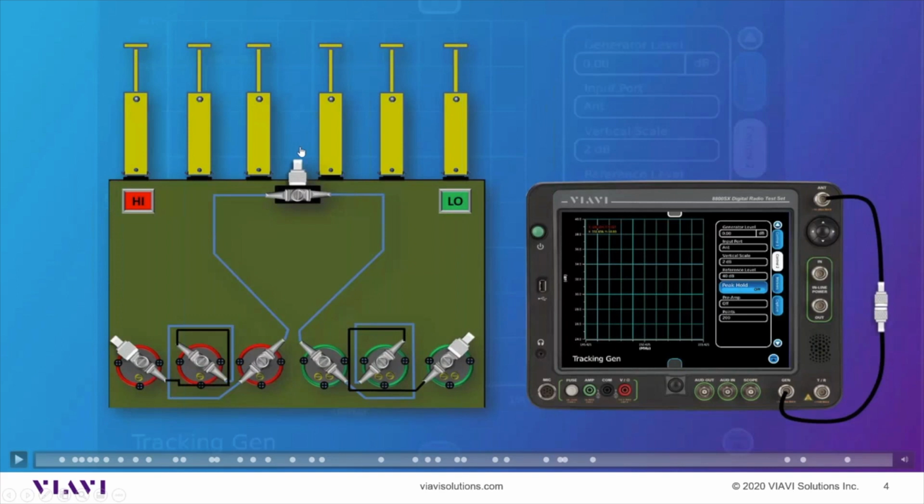So you need good isolation between the two, and that's what these duplexers do. The duplexers allow you to transmit and receive on a single antenna, and that saves you cabling and extra antennas, so you can be more efficient on your site setup. So basically that receive frequency is going to be coming down that same antenna that our transmitter is going out, and it will be going through the 3 resonators on the low pass side and then out to the receiver.